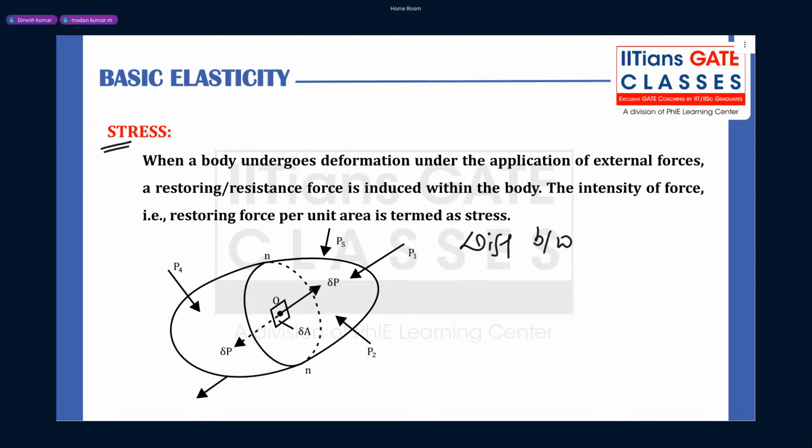Sir, stress can take deformation, but pressure can't. Deformation can't take place in pressure. Pressure will also change volume, no? It's not like that. See, pressure changes volume, right? So it's not like that. The difference between stress and pressure is very simple. Both have the same unit. Stress is a tensorial quantity, not a vector. It's a tensorial quantity, Anand. And pressure is a scalar quantity.